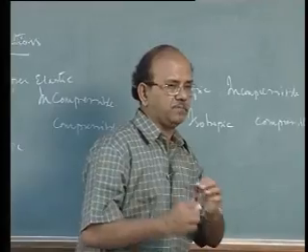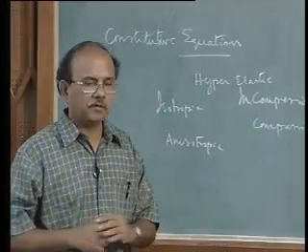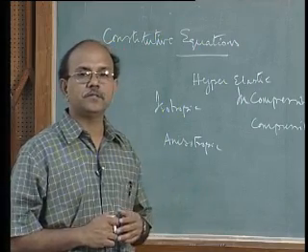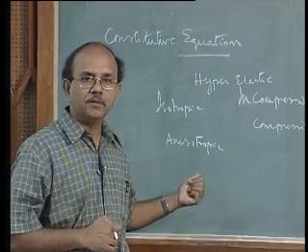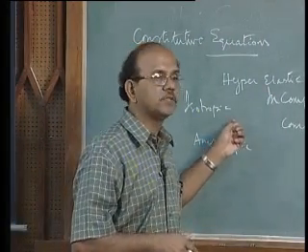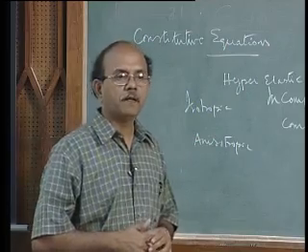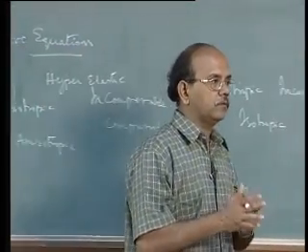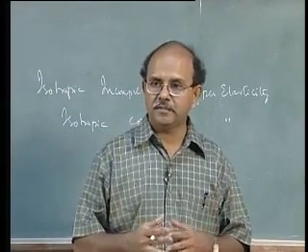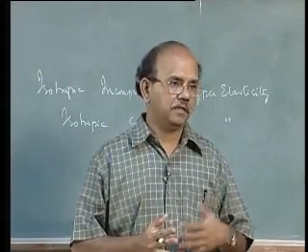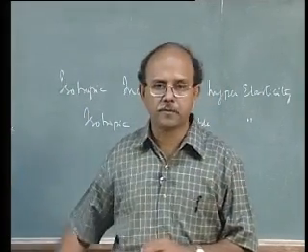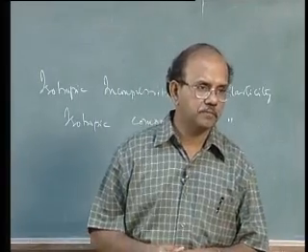Now, before we go further, because we made this assumption, let's just check what this anisotropy is physically, what it means, and why for many problems we can do away with anisotropy and use isotropic materials. For many practical problems, for example, if you take tires, I talked about hyperelasticity. Most of them are incompressible hyperelastic materials.